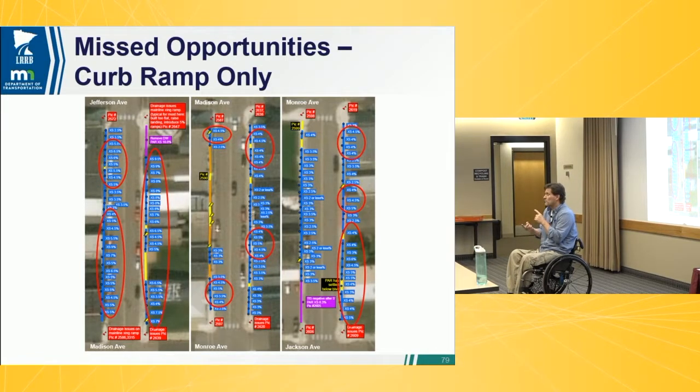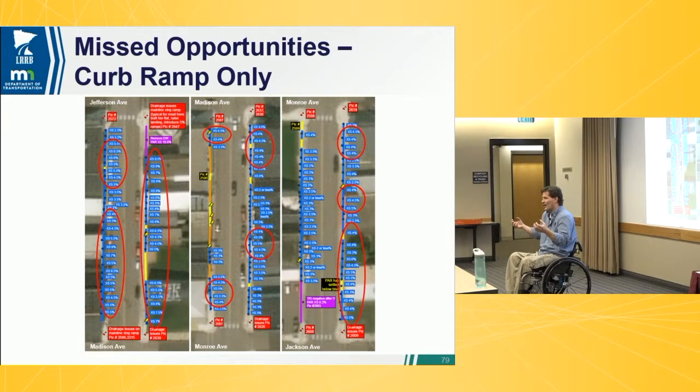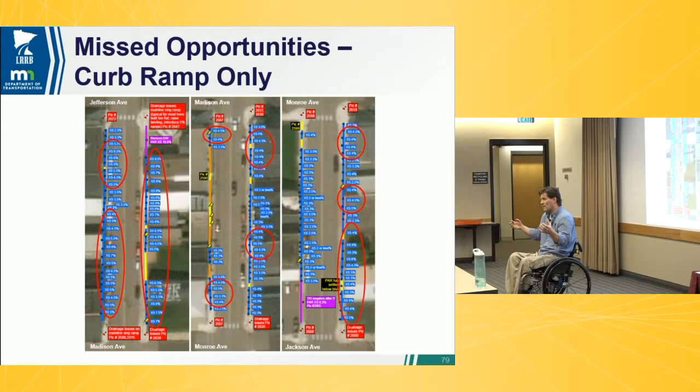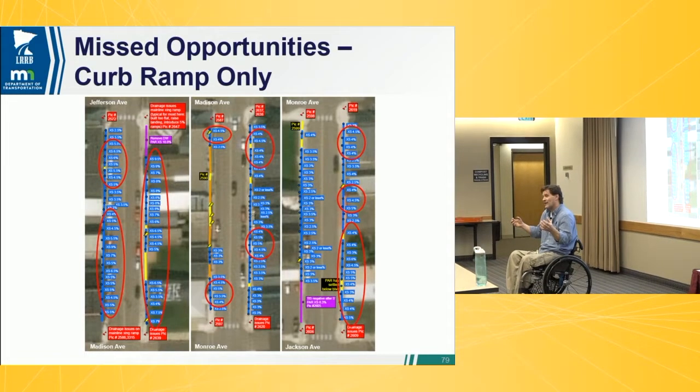They actually ended up replacing all of the sidewalk in this area, but didn't change any of the cross slope like MnDOT would have wanted from an accessibility standpoint. So neither side really got what we wanted. Obviously, if we'd looked at this more holistically and taken out those 3 blocks of curb, it would have cost us about 60 grand. Remove and replace, because we're already doing the corners, so it's just a linear section, and we'd just leave the catch basins where they were.